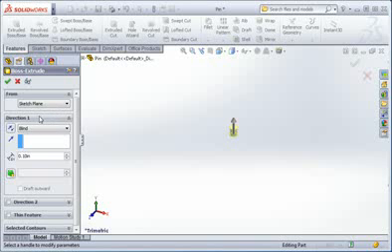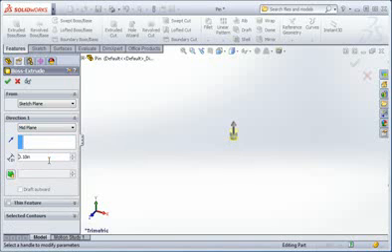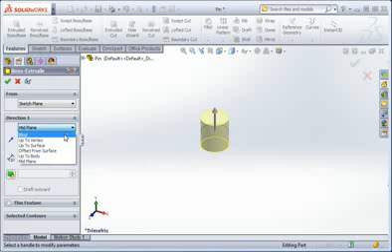The Direction 1 section controls the end of the extrusion. We're going to use the Blind option, which extrudes the profile a specific distance from the sketch plane. Most of these options require existing surfaces or reference geometry, so we can't use them now. But the Midplane option extrudes the profile above and below the sketch. Half the extrusion extends above the sketch and the other half is below the sketch. Select the Blind option.